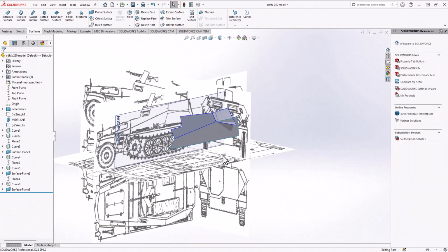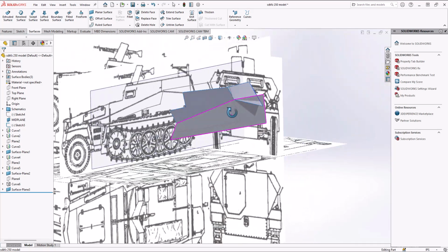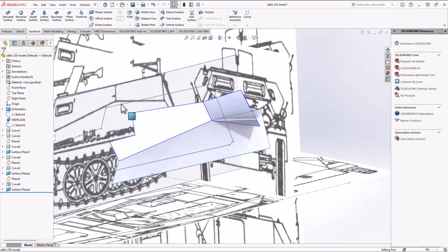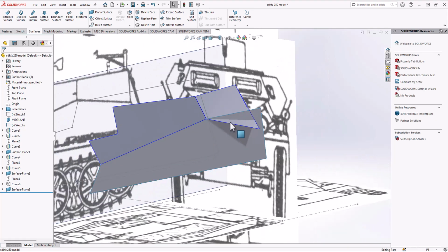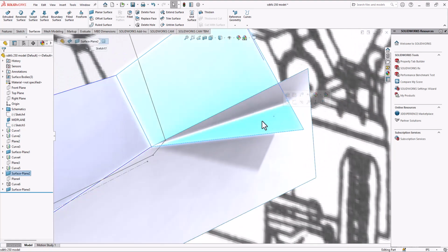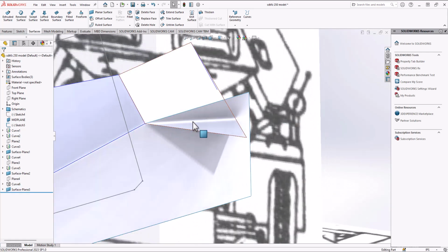Okay, so just as a side note, I'm doing the plates, and something that might be good to mention is sometimes you have a point where three plates meet, and it might be hard to align the pieces exactly. So what I do is I actually overshoot. So I've got this plate extending through this plate. They should be meeting at this line, but if I try to do this plate exactly at that line, I might be slightly off, and then you have some zero thickness geometry errors and a bunch of stuff.